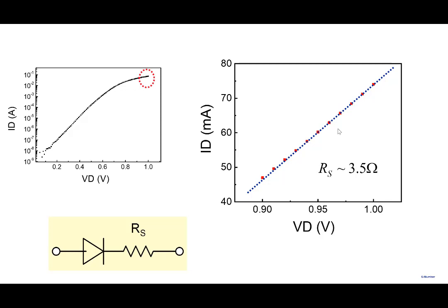That leads to power dissipation and all kinds of other issues. So we would like to keep the diode voltage small, and therefore we would like to operate in the exponential region. For that reason, we restrict ourselves to under 0.7 or 0.75 or so. But you clearly see that you can operate at 0.9, you can operate at 1, you can operate at 1.2, but the voltages are larger. The diode is more like a resistance.